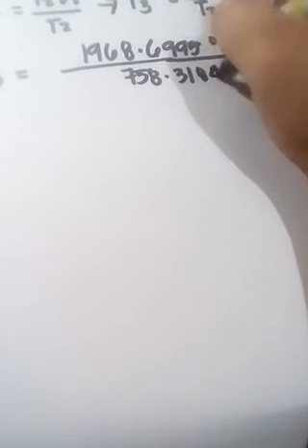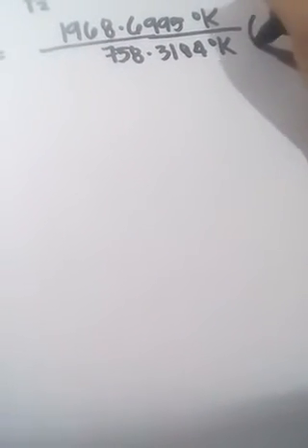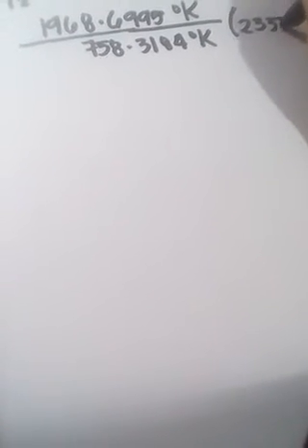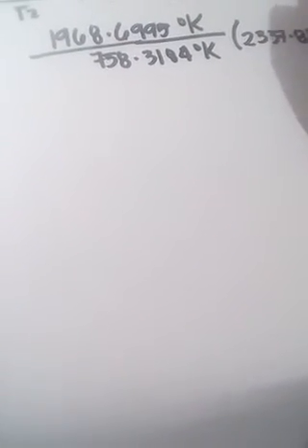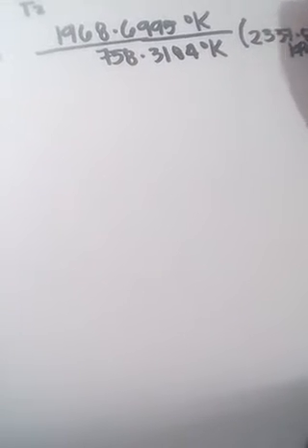Therefore, P3 is equal to T3, which is 1,968.6995 degrees Kelvin, over the T2, which is 758.3184 degrees Kelvin, times the pressure 2, which is 2,337.8305 kilopascal.